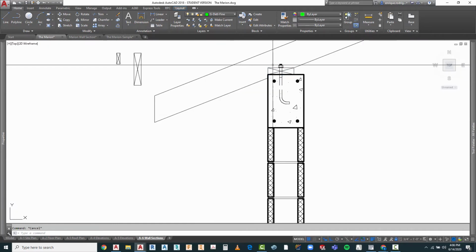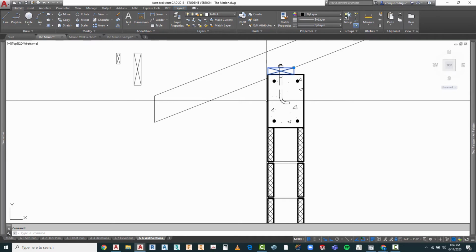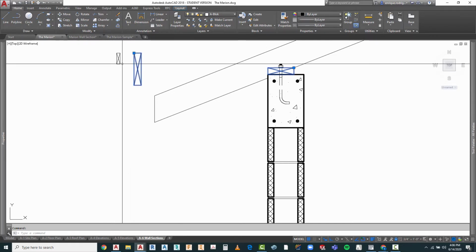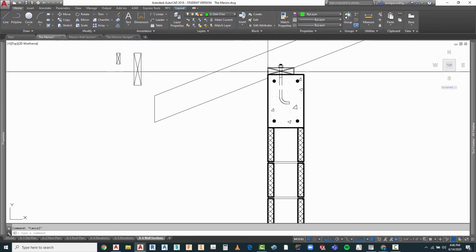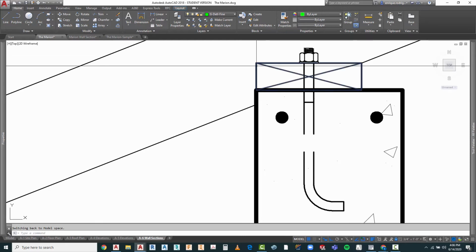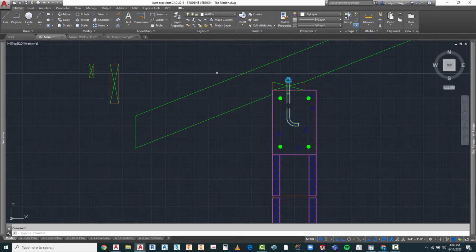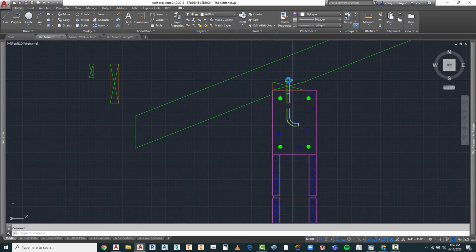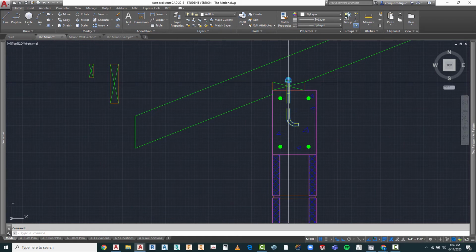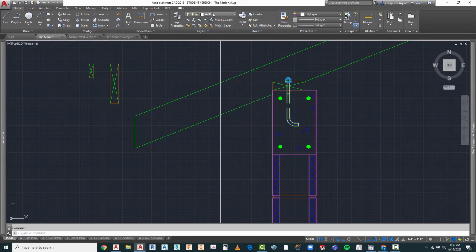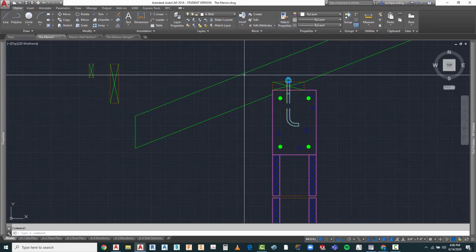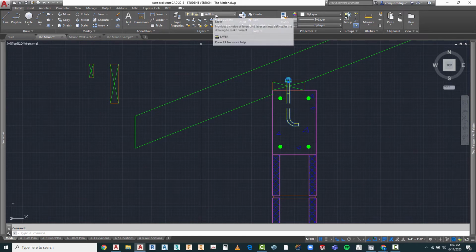So I'm going to take this block, this one, and make sure to change my exterior perimeter of it to a different layer. Now again, these are blocks, so if you highlight it, that layer will not show up. That G detail thin or G detail pattern doesn't show up there. Why? Because they're nested. Those layers are nested within a block layer that we've created.